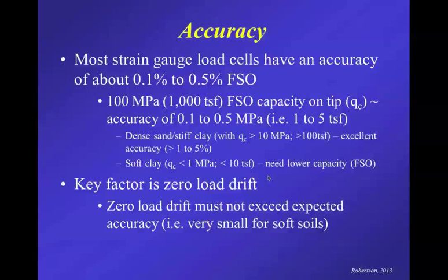So often what happens is if you're not 100% sure about the site, then typically you use a high capacity cone first, punch a few holes, verify, yes, that you have soft sediments and that you would like improved accuracy and that you don't have any dense layers that you have to get through near the surface, and so you could then use a lower capacity cone to improve the accuracy and then to check it against the higher capacity cones.